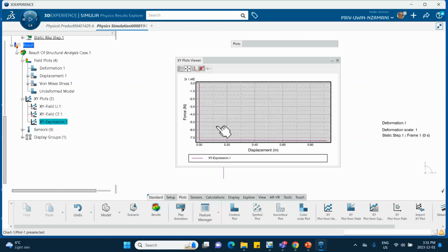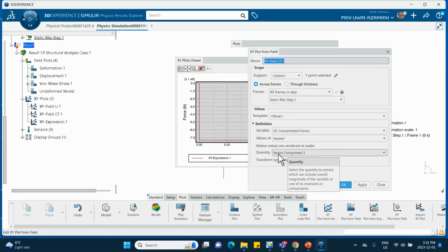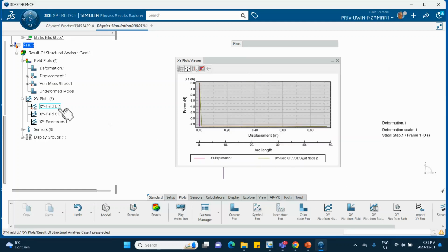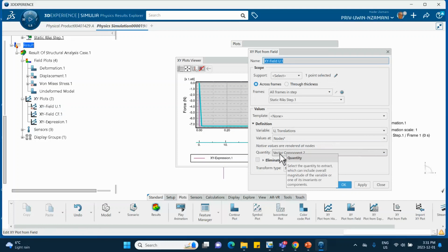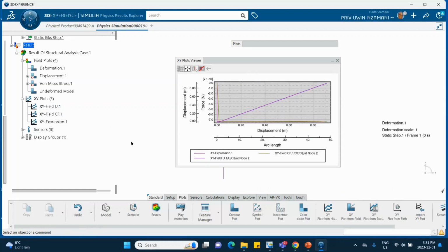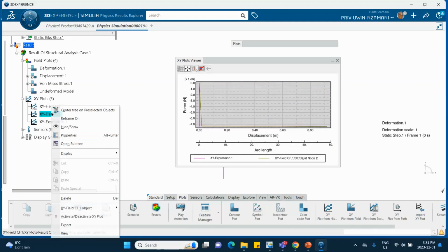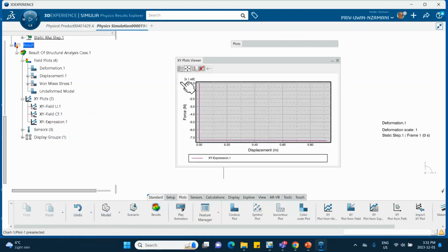Okay, so what I'm telling you is this: I don't know why he's plotting. He should be plotting force in the direction z, and this one also force in the direction z, but he's doing direction y. I'm not sure, but I wanted to reproduce for you. So let me deactivate these. Let me show you again. Deactivate this, deactivate that, and there. This matches his plot. And it shows you that I did not know anything about this buckling load of 7.4. It pops up by itself right there.